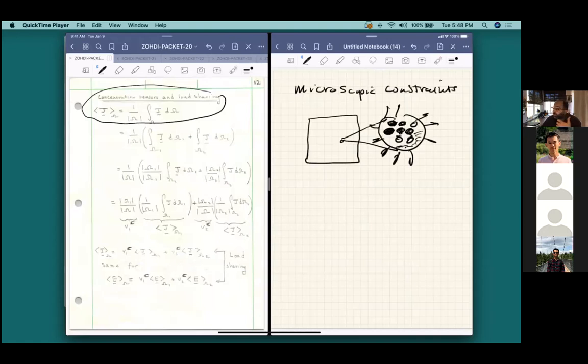Now, depending upon one or the other material, one part of the material might fail depending upon how much of the load it has to take. You can imagine if you think about your undergraduate days in strength of materials, you may have seen problems in composites or steel design, where you pull on a piece of material and you ask yourself how much of the stress is carried by the steel, shown here, and how much of the stress is carried by the surrounding concrete or things of that sort.